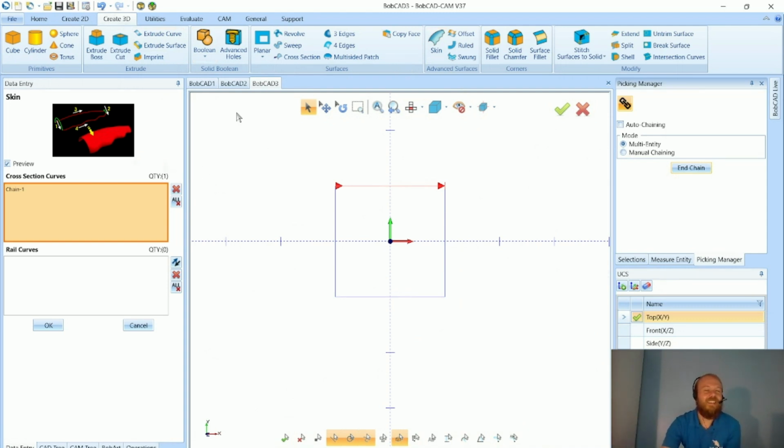Okay, so over here at the top left corner, you can see in your skin surfacing function, you've got 1 and 2, and then you've got 3 and 4. So exactly as I described, the 1 and 2, and then the 3 and 4 going down, or it could be the other way depending on your geometry. It could create a different surface one direction or the other if you have a very complex shape.